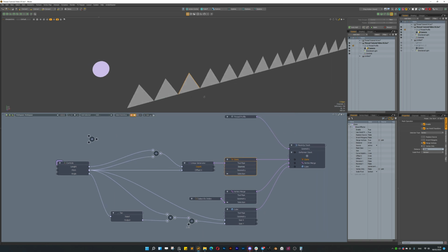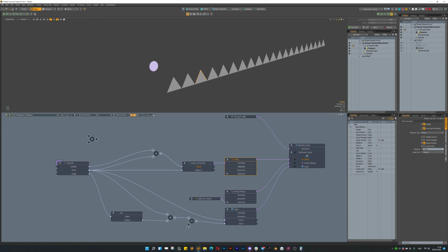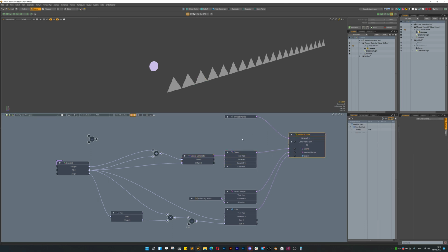So next step is to make curve or polyline from this edge. I add here operation edge to curve, and what kind of selection we make. We have one like this, so let's make it so that we make selections, assign set. So we make selection set before we do the clone, and we select these two edge set.